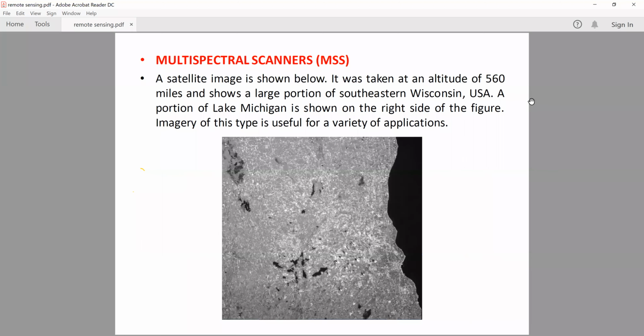So it basically depends. Over here, it's an image drawn up by a multispectral scanner. It scans the area, takes the reflectivities of objects, and wherever a particular reflectivity comes up, it then classifies it based on that. So wherever there would be houses of a particular material, their reflectivities would be the same, and it can classify that over here we have the covered area in terms of houses, over here we have a lake, over here we have a green area, let's say.